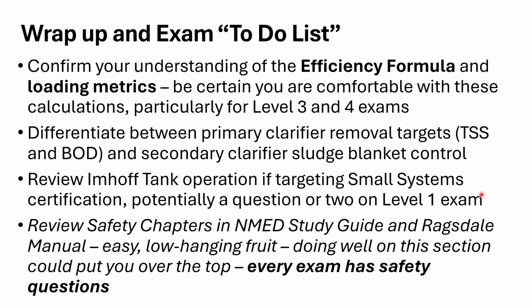Okay, for your level 1, possibly level 2, but mainly level 1, or your small system, if you decide, oh my God, I love this so much, I want to be a small system operator and get certified. Understand the Imhoff tank, how it operates, the fact that gases are going to escape off the side and not bubble up into the sedimentation basin. And then understand on the combined unit, the clarifier and digester unit, there's a boot seal that's going to prevent that gas from going back into the clarifier sedimentation portion.